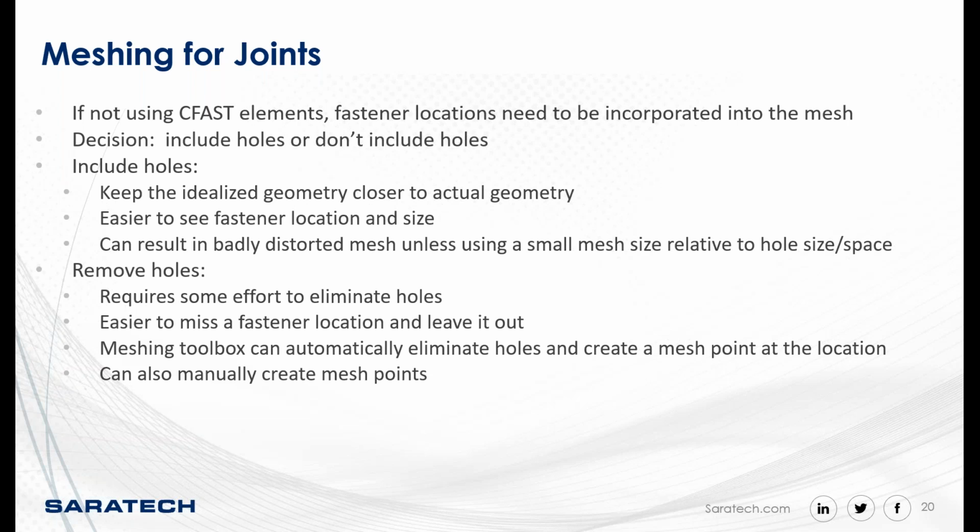Now remember, we're not trying to get stresses. And if we leave that hole in there, someone might say, well, having the hole there is a good idea because that way I get the effect of the hole in the stresses. But we're kind of fooling ourselves if we think we can put a fastener element in there and get any sort of realistic stress around the hole, right? Because we don't have all of those things like contact, and friction, and clamp up, and head fixing. None of that is actually in the model. So even with the hole there, it's not really going to help us get good stresses. Again, all we're really after is stiffnesses, so we can get the loads.